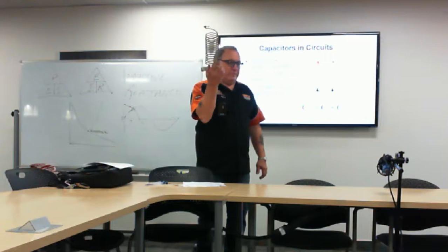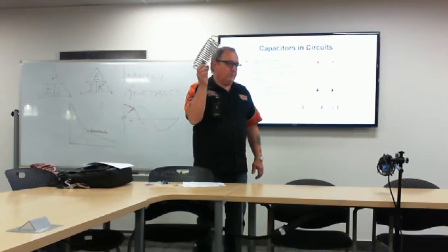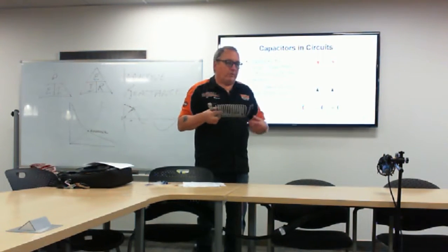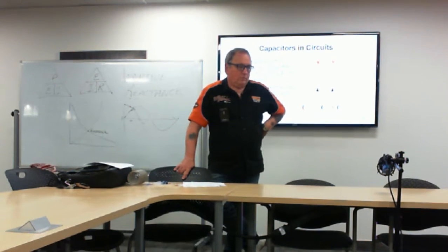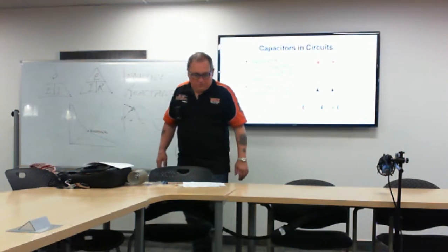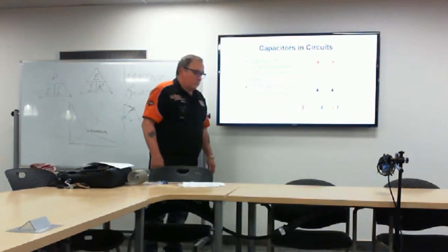The trap has a parallel circuit, and it only passes a certain RF frequency. Let's say you're on the 40-meter band, it'll block the ends of the antenna off, because it won't go to the 80-meter band. So the ends of the antenna are blocked, the antenna is shorter, and it works on the 40-meter band.